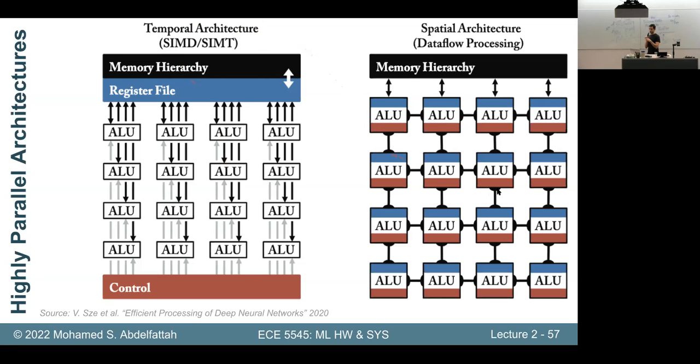And usually people build that in a custom ASIC or on an FPGA or something like that. So you would lay out your instructions spatially, you would pipeline it, and that's how you can get the efficiency of complex applications that don't really work well in the SIMD fashion.